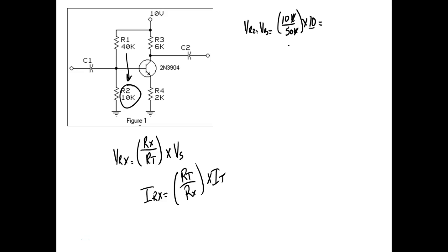Does that make sense, Charles? What I can do right off the bat, which makes my math easy, is see it's got K on the top and K on the bottom, so they cancel. I've got a 0 there and a 0 there, so they cancel too. So that means that resistor is going to drop 1/5 of the voltage. Period.